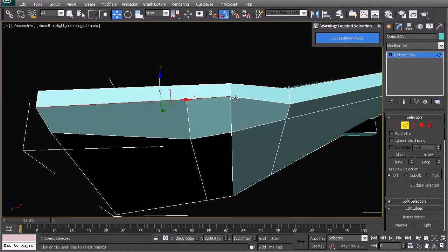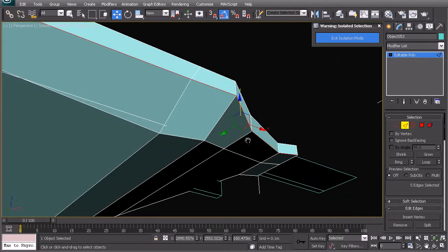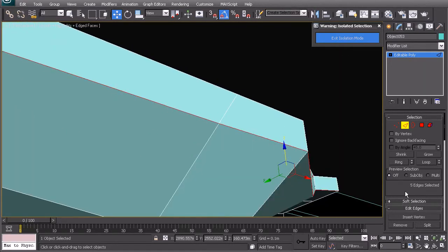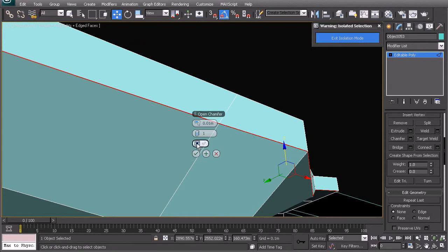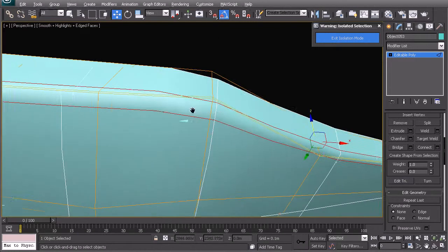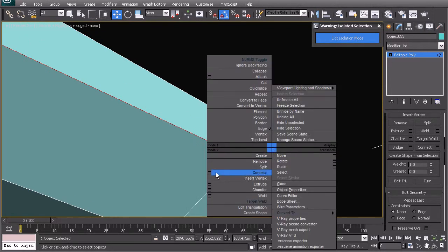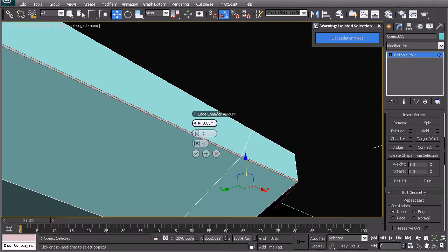Anyway, I'm going to just motor on forward and select this entire edge. And I'm going to add a very small chamfer to that. Perhaps, here's a bit of trial and error, but perhaps 5 centimeters. And then we can just gnomes toggle that and see if that's too big or too small. Maybe we can go a bit tighter. So let's chamfer that again, this time with a much smaller amount.